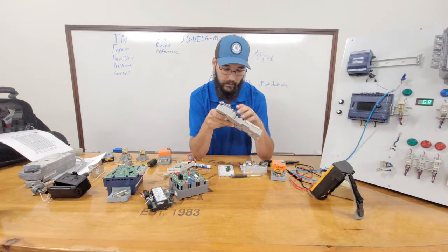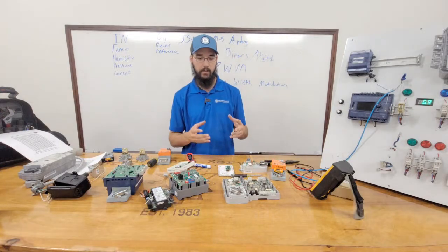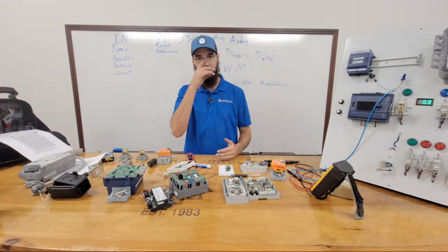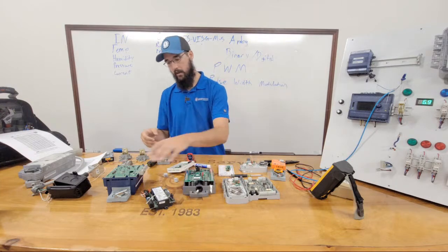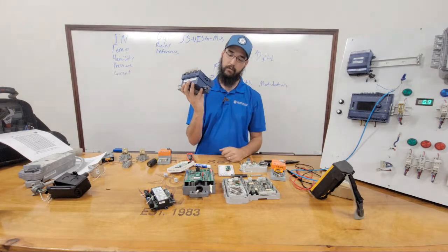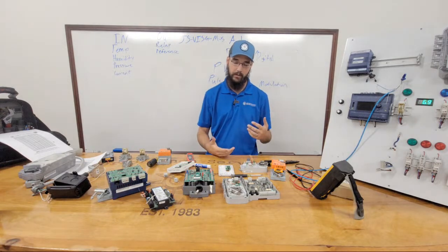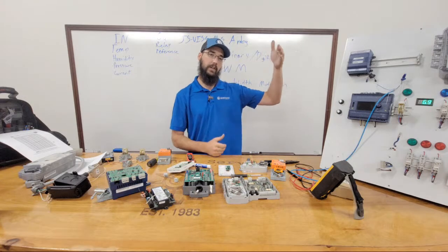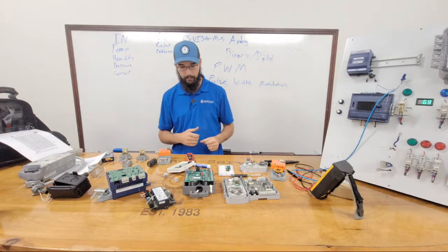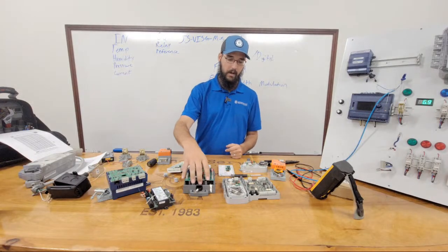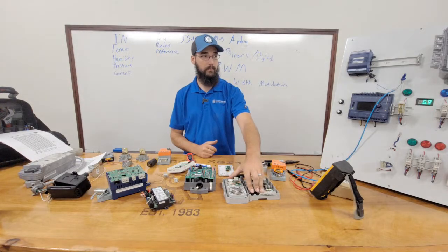So on a VAV specifically, or a fan power box, that is going to be what is monitoring how many CFM you're flowing through it. This Johnson controller is there. Distech, they've got them back over here. So usually you'll have some kind of poly tubing running from the controller to the inlet of the fan power box or the VAV box, whatever it is you're using. And there's some really critical things to keep in mind. Ultimately, it's really easy to get these backwards.